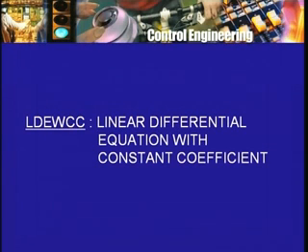Now the problem that therefore one can consider is the following. The behavior of the motor is described by these two linear differential equations with constant coefficients. Suppose we apply some armature voltage and keep it constant. So that is a special case, of course. Later on when we think of feedback, the armature voltage that is applied is not going to be kept constant because it is produced by a generator, etc. But for now, let us consider the special case when the applied armature voltage is just a constant. It does not change with time, 230 volts. From the moment the motor is switched on, the applied voltage is kept at 230 volts.